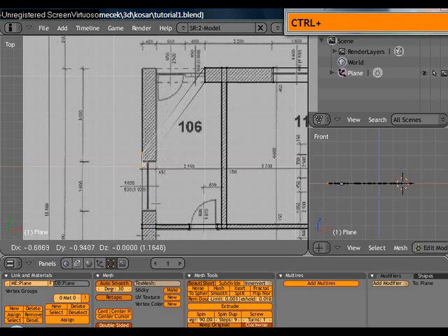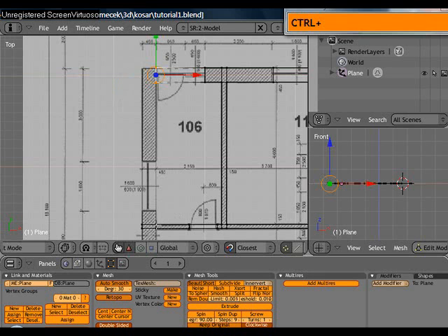And you probably don't see use of it. If I like to align it down here, it's not much use, but what I can do is lock my extrusion in this direction, which is the X direction in my case, by pressing the middle mouse button, or I can just press the X key to do the same. And now when I move my cursor close to this vertex here and hold Control and click, it will align only the X direction of those two vertices, so they'll be aligned in the X, but the rest is going to stay where it was.